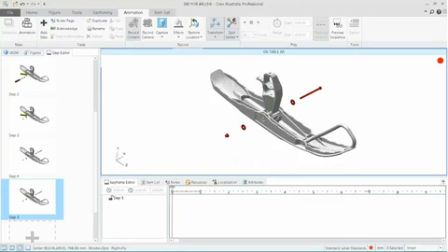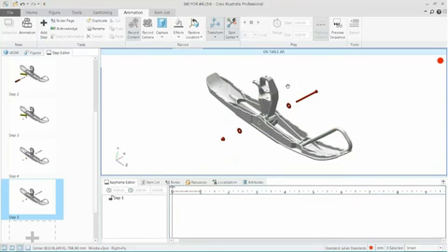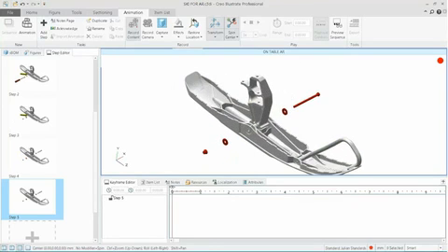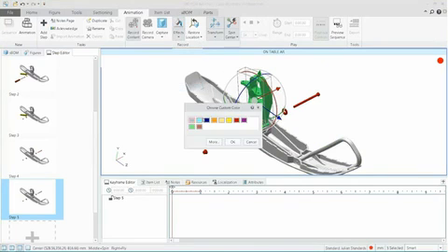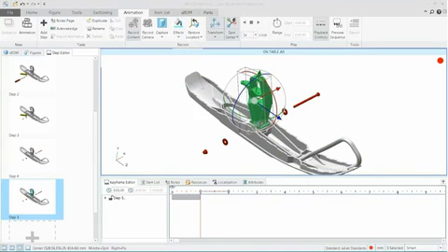Let's go ahead now and interact with the spindle itself. Now the spindle contains additional types of hardware. I have the ability in Creo Illustrate to easily come in and select all of those components just by box selecting around the geometry itself and interacting on it. So now I have the spindle and all the hardware selected. Again, we'll go ahead and change the color and we'll translate just to be consistent.